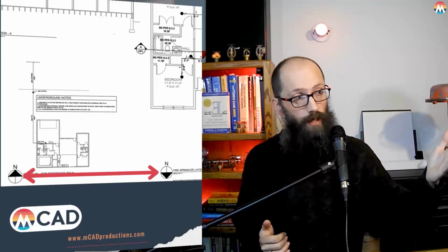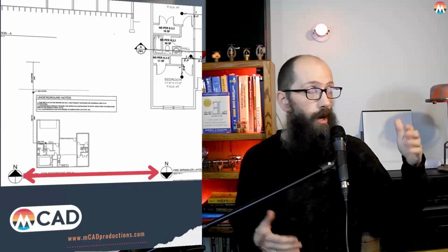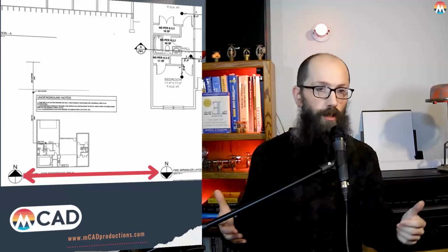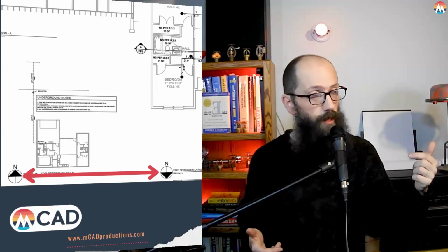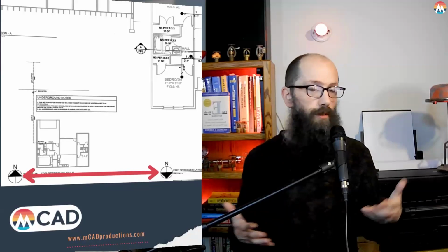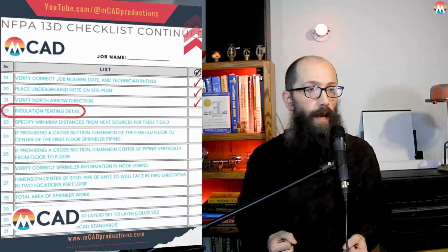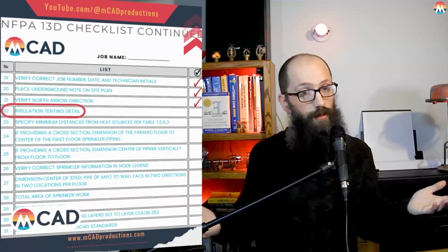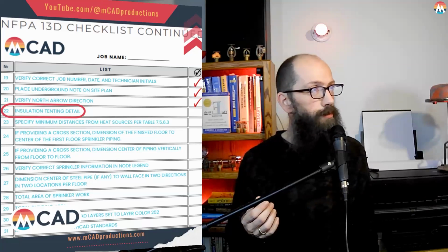And so on the left, we have a site plan. You can see the north arrows pointing up. And on our actual plan, it's typical to put the front door at the bottom of the plans, also in architectural plans. And so when we flip the house around to do that, now the north arrow is rotated around. And so this is the correct layout for this site for the north arrow. But these are the types of things that we were talking about here. All right. And again, it kind of seems like a minute detail, but some jurisdictions really want this. So we just go ahead and give it to everybody as long as it's easy to obtain.